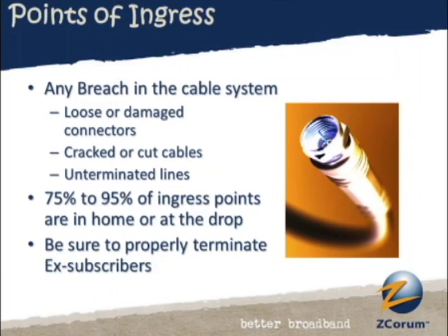And in some cases, we've run into pain because we tried to do the right thing by trapping the frequencies that weren't in use. And then we went back and under DOCSIS 3, we started adding new upstream frequencies, and now we've got to go out and change all of our traps out. So it's one of those things that we've struggled with throughout the history of cable operations. Mm-hmm. And just because you've got this place where noise can get in, that doesn't necessarily mean that you're going to have noise in your plant. Absolutely correct. There's got to be a source as well.